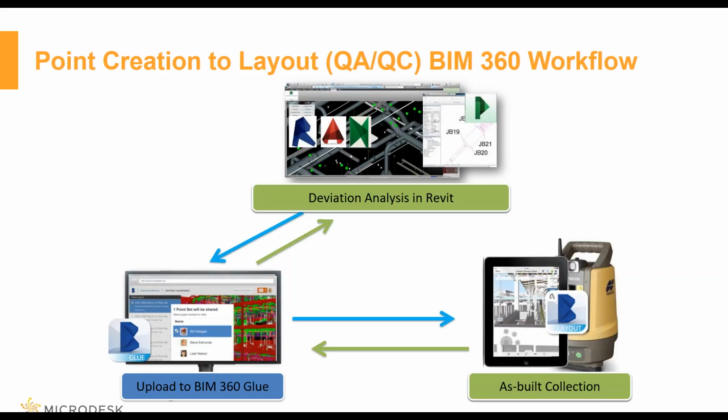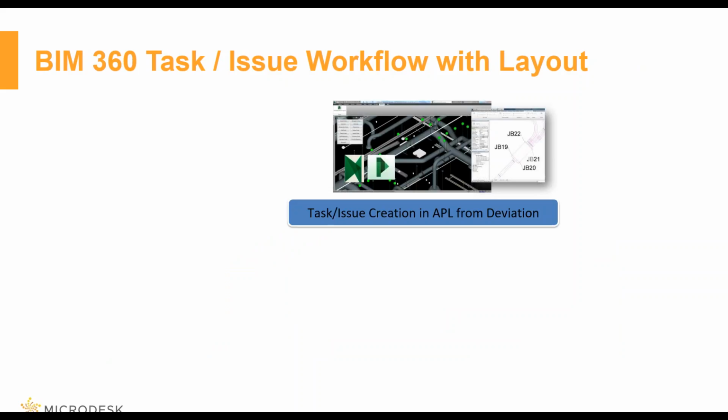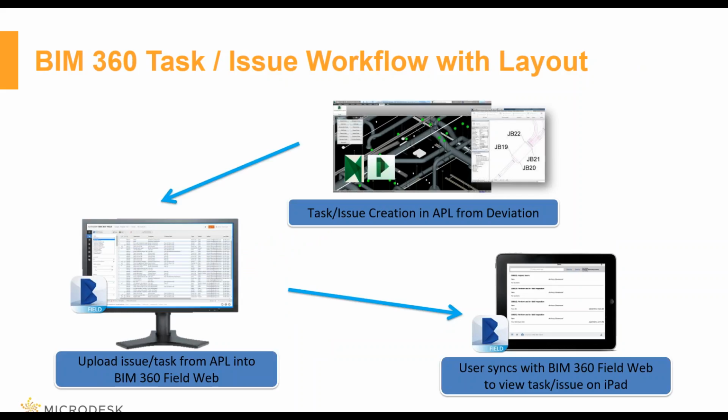And if I want to, I can then create an analysis inside of our tools to find out, okay, well, where are we off? You know, is my floor actually flat? What's the percentage of being off? Am I going to run into problems because they shifted things in the field? And let's say that they actually do shift something in the field. I can then create something called an issue in BIM 360 field directly from this. So we're out in the field, we do this, we come back, we realize that something doesn't line up. That can automatically send that data and tie to BIM 360 field, so that way I now know, okay, there's a problem here and we have to deal with this. So we need to alleviate that.